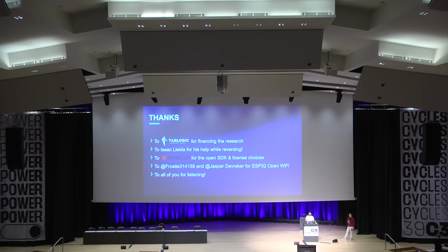You can use the Golden Binary project that I have uploaded to the ESP reversing repo, and you can look for all the code that's being executed there. It is quite a mess. If you're going to go down that rabbit hole, I recommend you write me, because there's a whole new real-time operating system there on top of FreeRTOS. So there are 2 real-time operating systems running in the ESP, and one of them is from the peripheral manufacturer, which I believe is Riviera Waves, but I cannot confirm that.